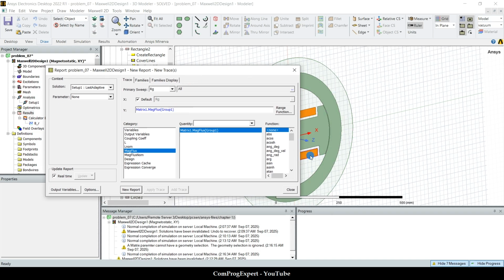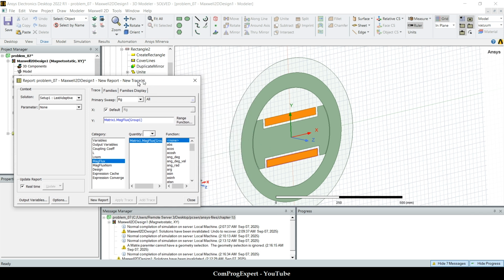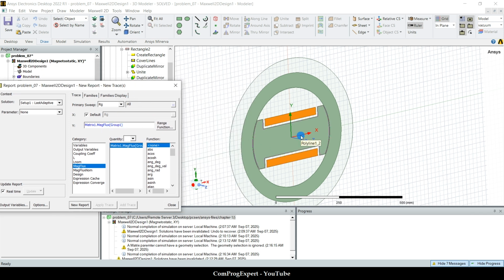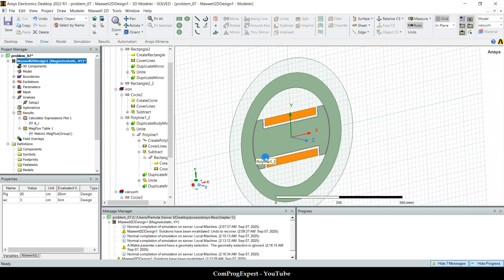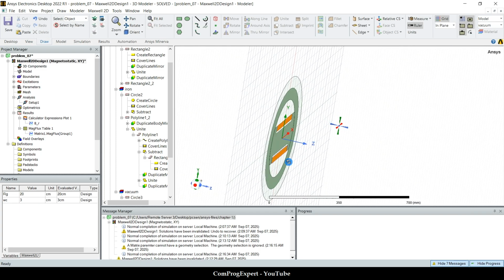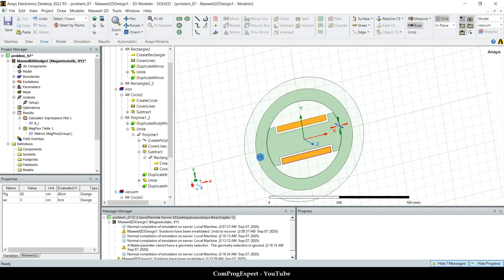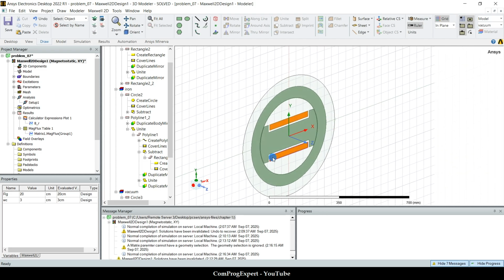But this flux linkage is calculated considering the depth of the problem equal to 1 meter. We didn't set the depth of the problem for the software. Okay, so this is the magnetostatic simulation for one cross section of the motor. So we need to include the depth of the problem in our calculations. As long as we increase the depth, we have more and more flux.